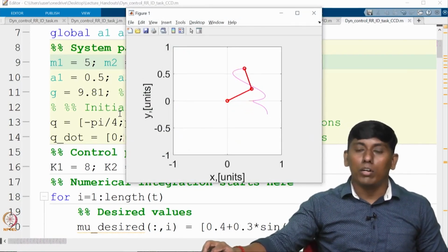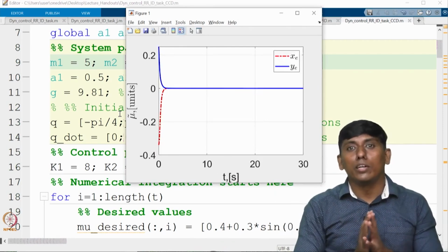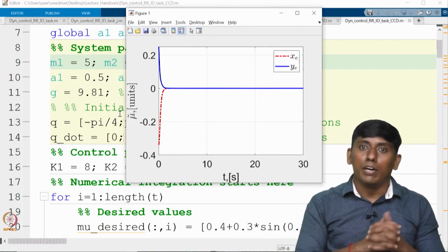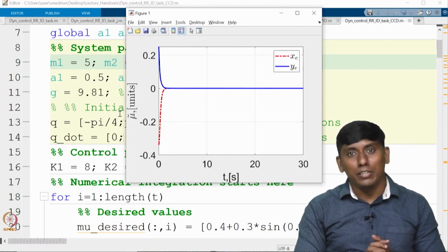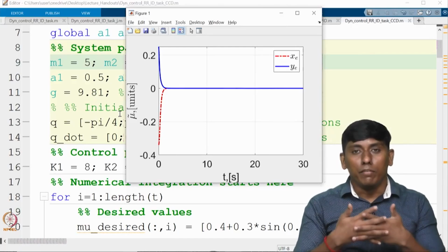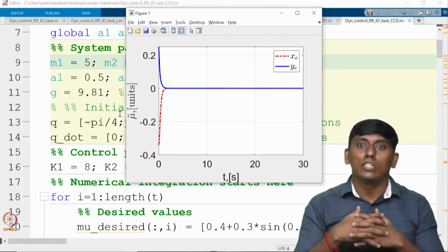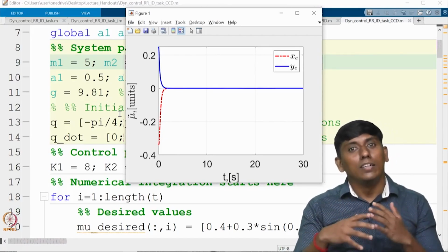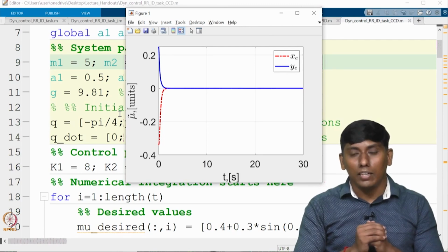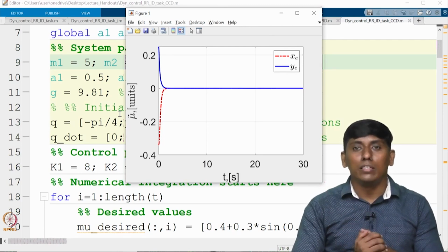With that, we have seen the motion control overall. We talked about the joint space scheme, then the task space scheme. Finally we ended up with the merge, which is what you call the cascaded design. The outer loop would be seeing the task space, and the inner loop would be in the joint space.